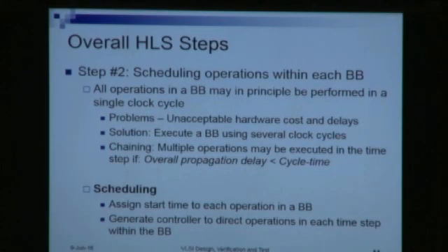When we divide things into different time steps, I can share the same resource at different time steps, which is not possible if I do it within a single clock step. And also, it will increase delay. Why? Let us say this clock is not only feeding this basic block, it is possibly feeding many other basic blocks in different parts of this module, and in other modules of the whole application. So all of these will have to incur this delay, and there could be very small basic blocks as well. All basic blocks will not be this big.